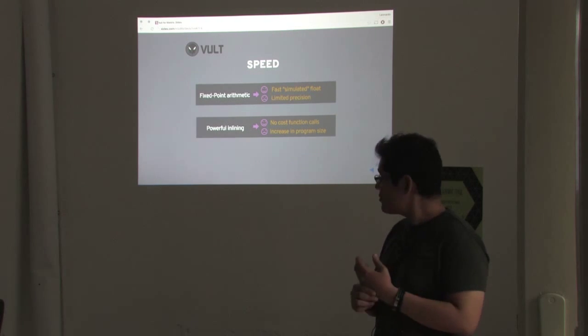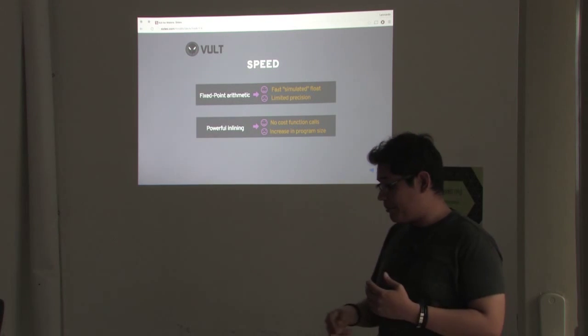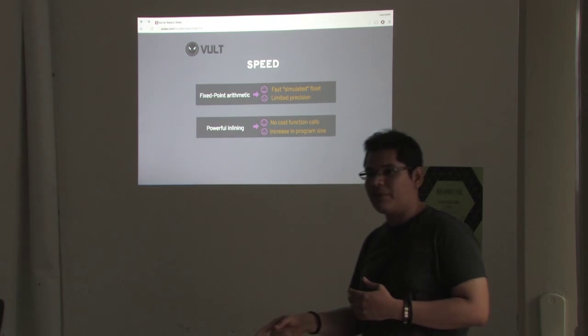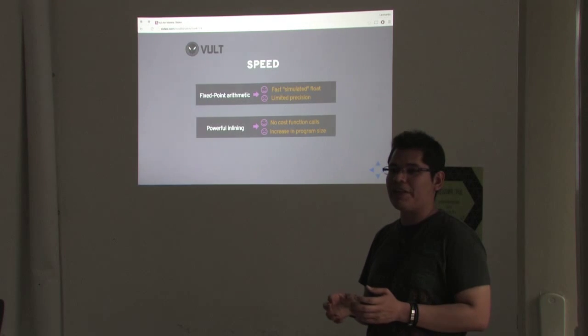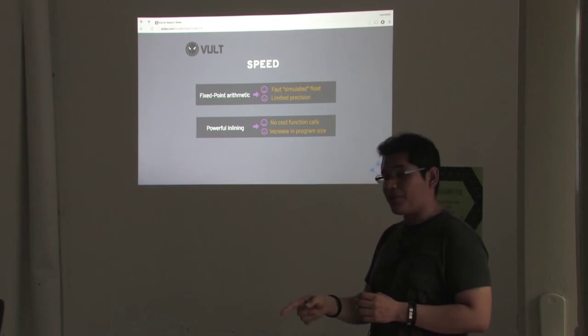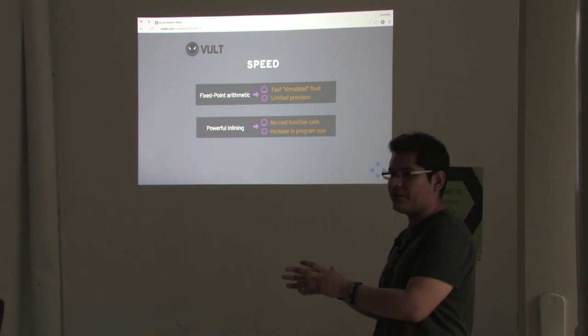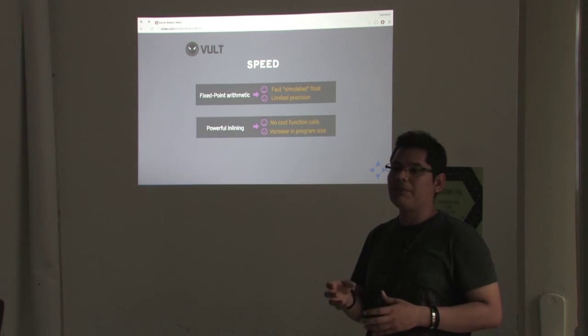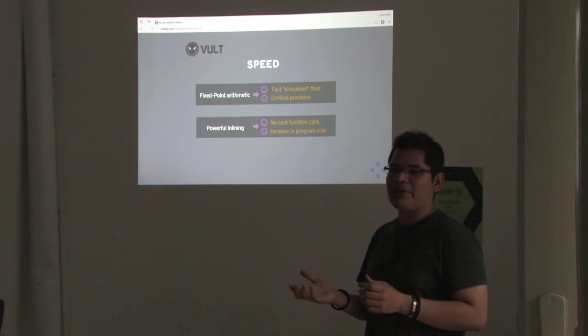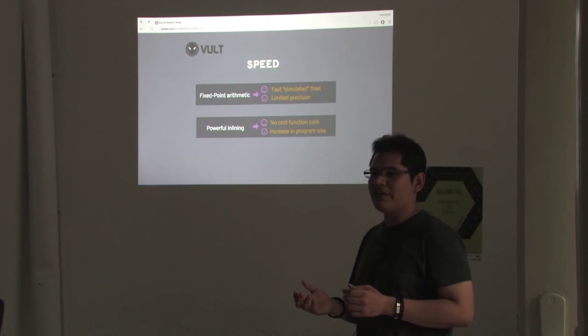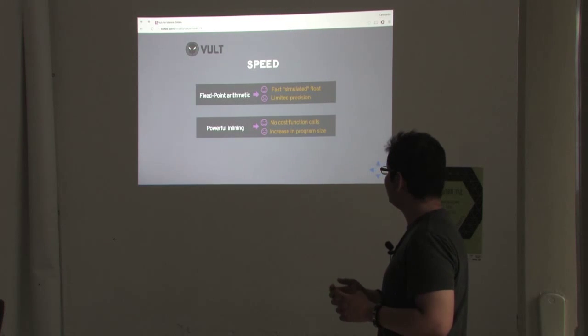So it just comes natural. But when you're programming small microcontrollers, a floating point operation is a very expensive operation if the microprocessor does not have a specific unit. If you have done Arduino programming and you use a float variable, you may find out that your programs run like 10 times slower. It's not possible to achieve that.